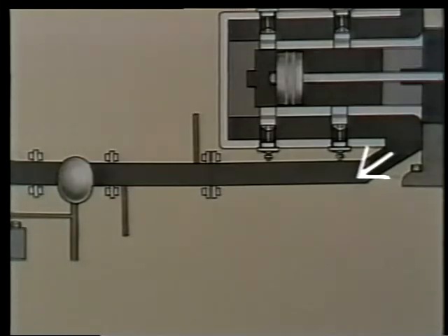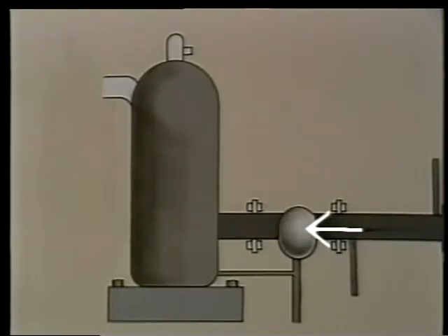From the second stage cylinder, it flows to an aftercooler, where cold water cools the air before it's transferred to the receiver. Cooling has again added drops of condensation to the air. It's passed through a moisture separator. The flow of air is directed into a tight spiral. Water droplets are thrown out by centrifugal force and run down the sides of the vessel to a drain. The air flows from the moisture separator directly to the receiver. The air's now been compressed, cooled, and dried.